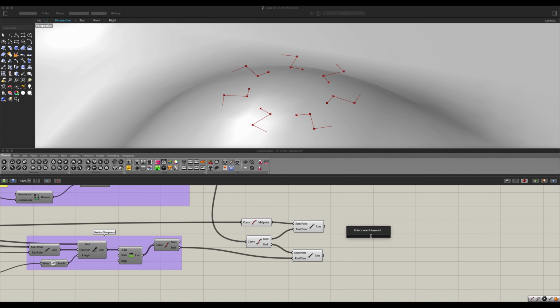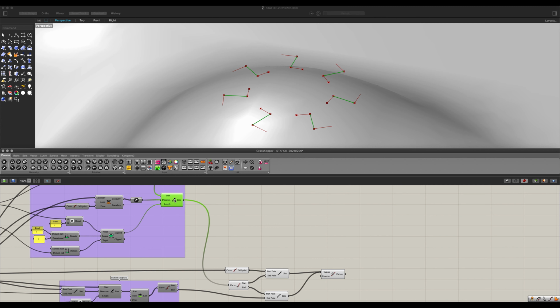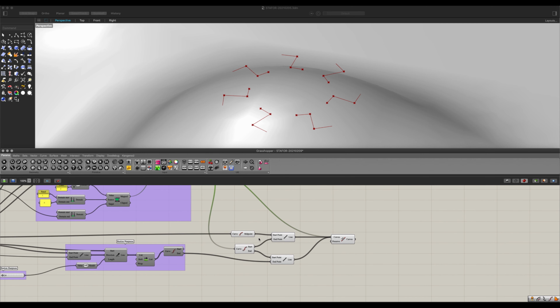Okay. Now we can get ourselves a join curves. Let's bring in this one there. And also we want to bring in our STL line back here to get ourselves our base shape. We can now hide this one here, also hide all of these points, like that.